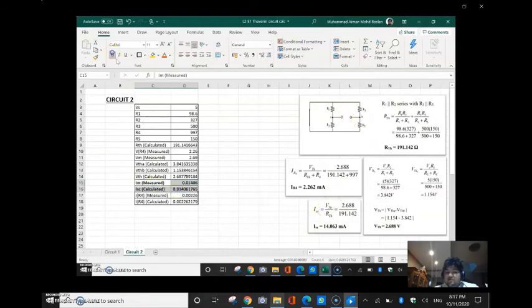As you can see, it approximates to the measured value of IM, which is measured using the ammeter across the terminal AB, of 14.617 milliampere, compared to IM, which is at 14.06 milliampere. And then we'll be calculating IR4 to prove the theory and see its accuracy. As you can see, the calculated value of IR4 is 2.2621 milliampere, whereas the measured value is 2.26 milliampere.